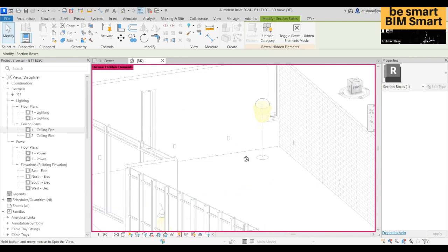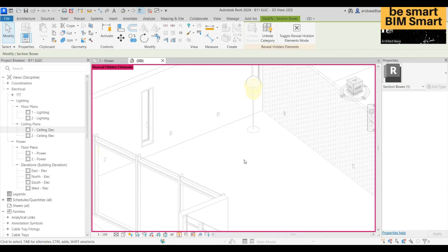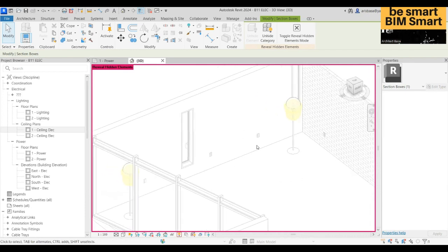In actual construction, I mean in Revit models that we use for construction, we will put the conduit and then we'll put on the cable trays where the conduits would run. Connect to the tray. Whether the tray is on a raised floor, sometimes we have raised floor, then they put trays there.